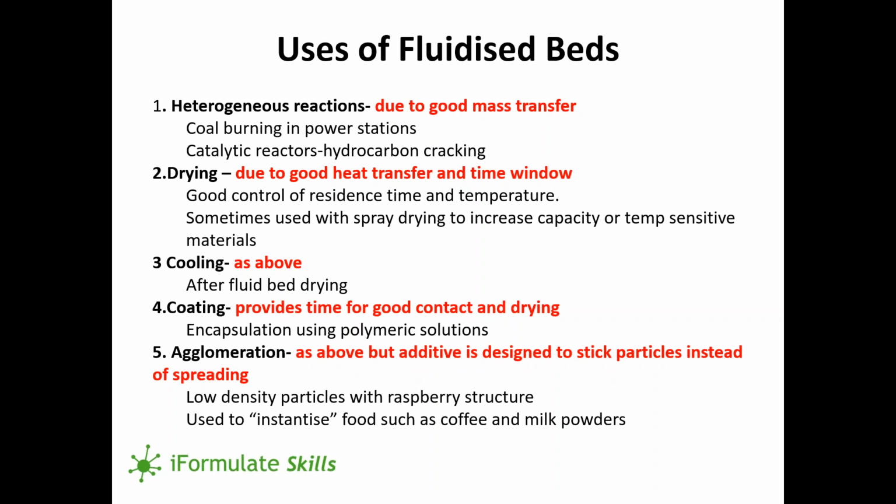This ability to move the particles around also gives us the opportunity to coat. So as well as fluidizing and moving the particles around, what you can do is spray a solution onto the particles, and with good control of the spray conditions, you can get the liquid to coat the surface of the particles. And typically you would use a film forming polymer solution that spreads around the surface, and as it spreads you provide hot air into the fluid bed, and that dries the liquid and forms a solid polymer film around the surface. So it's used a lot for protecting particles and also for coating them for controlled release.